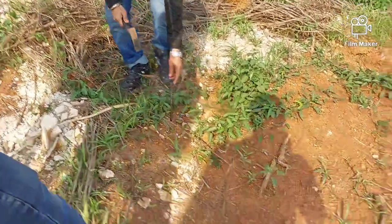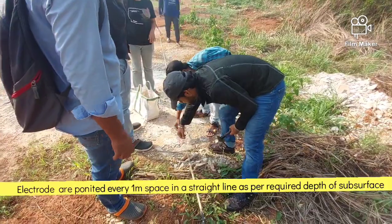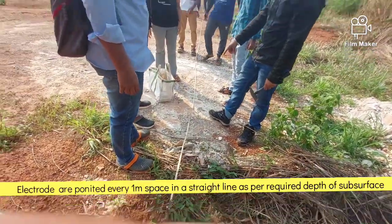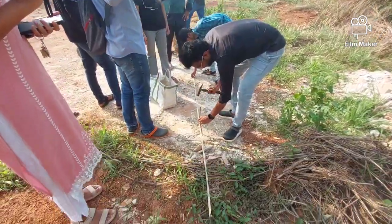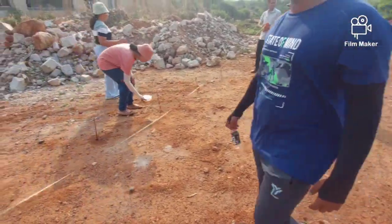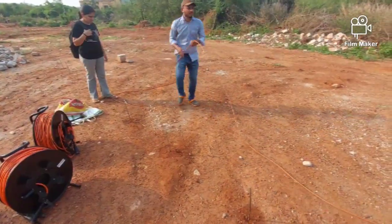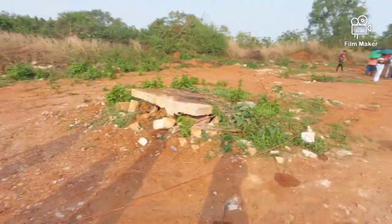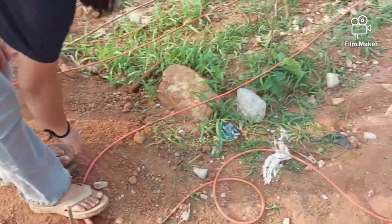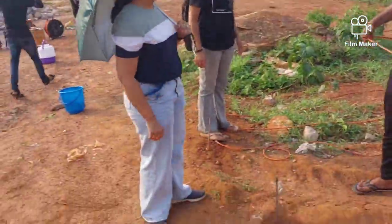It should be this. They should not deviate from it. The electrodes are placed every 1 meter, about 4 to 5 inches deep, in a straight line. Salt water is added at the electrodes to increase the conductivity of the loose soil. The multi-core cable should be laid perpendicular to the electrode line without any overlap of the multi-core cable.